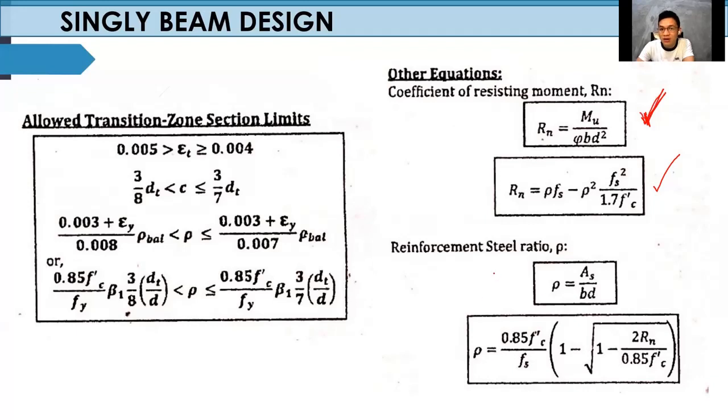So, reinforcement steel ratio natin, no, that is Rho. Diba? Rho is equivalent to As over bd. Then, same pa din, no? Diba? Sa ating slab, if you have your Rn, you can use that one or you can substitute that one to ating Rho is equivalent to 0.85 fc prime over Fy. Or, nasa slab natin, if it yields, this is our Fy. No? Same naman siya. Then, 1 minus the square root of 1 minus 2 Rn over 0.85 fc prime.